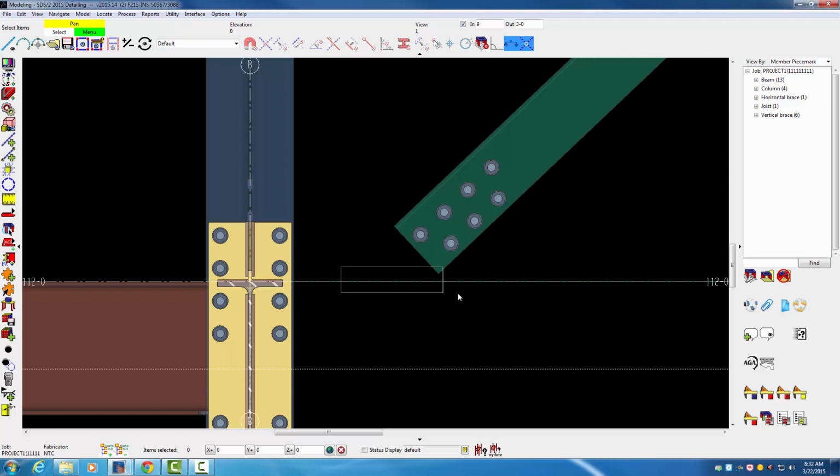if you put above your beam here, take your left button, select, and drag across, you can see that I found two boxes here. Them are actually the boxes to select the end of the beam, only that end of the beam. Or in this case here, it selected this one too, which is that end of that brace.